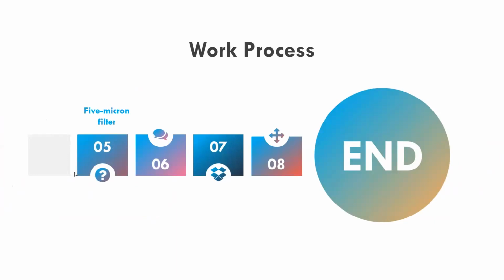Followed by 5 micron and 1 micron filtration filters. And these filters filter out suspended particles having size up to 5 micron and 1 micron. And each system also includes an ultraviolet water purifier to eliminate the pathogenic contamination which is caused by bacteria and virus. And last, an outlet tank to hold the treated water. And in order to benefit the community, the output tank will be kept on a tank stand so that the families can come and collect filtered water for their daily consumption.